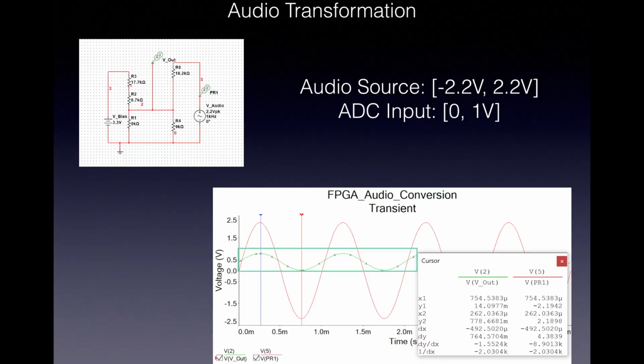To use a standard aux jack as a frequency source, two voltage dividers are implemented to scale and bias the input audio wave into a signal readable by the ADC.